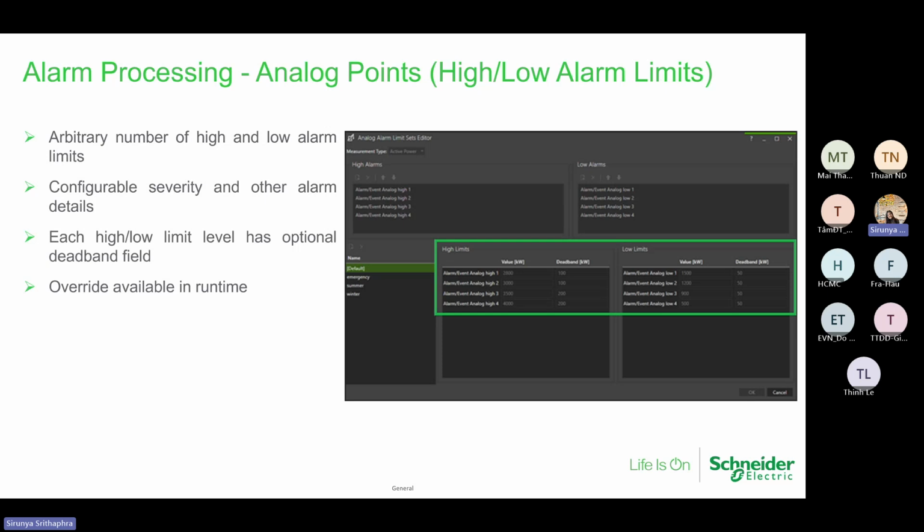DERMS normally uses megawatt because it needs the direction of flow. In some companies the generation is so much that sometimes you get reverse flow. If you have ampere, you wouldn't know which direction it is. That's why we use megawatt.